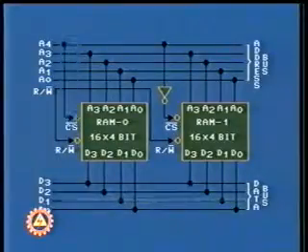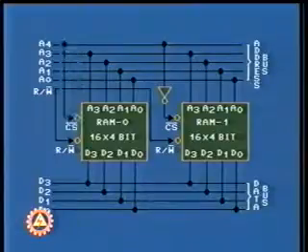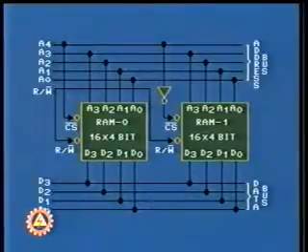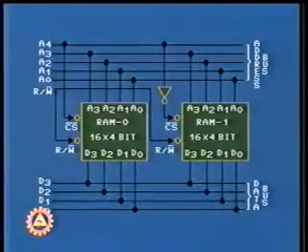The CS bar input provides for RAM 0 page address as 0 and RAM 1 page address as 1. Here, the starting address of the memory block is 0. The starting address of a memory block is called its base address.